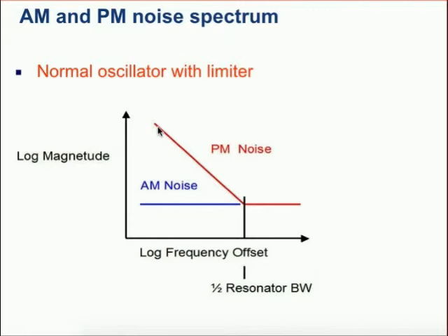So this is the minus 20 dB per decade slope, the Leeson slope, and in our simplistic model this will go up, and at the oscillator bandwidth, say that's here, the plot will then go horizontally at a constant power spectral density to zero frequency. But what happens in a practical oscillator is at some frequency, the flicker corner frequency, there are other more complicated effects that cause the noise to go up.